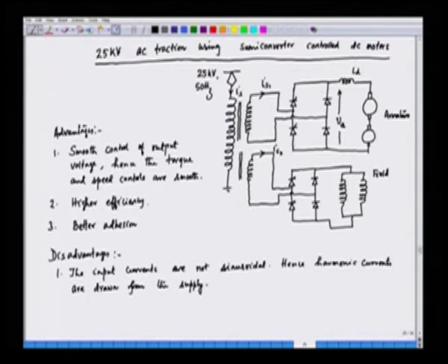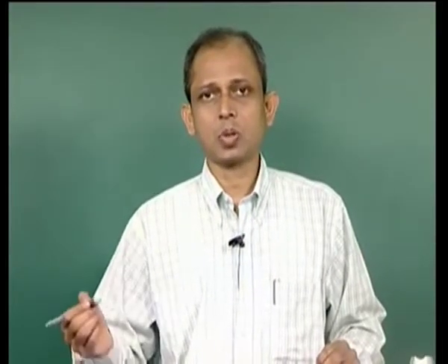In fact, when we draw harmonic current from the supply, the system gets polluted, and the power system also gets polluted. So, we have the problem of power quality. And in fact, when we draw harmonic currents, the transformer gets overheated due to the increased losses because of the harmonic currents. And what about the other drawback?